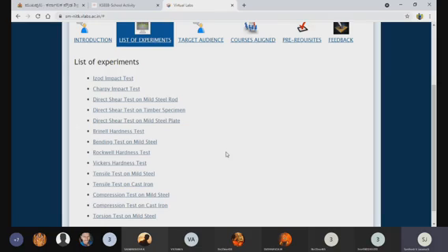All the parameters: load, scales, selection of material itself, dwell time, minor load, major load, all these activities are very, very important. These are the practical activities. We make sure of these activities while conducting the experiment. Also, we have to have the information regarding what exactly they all do.